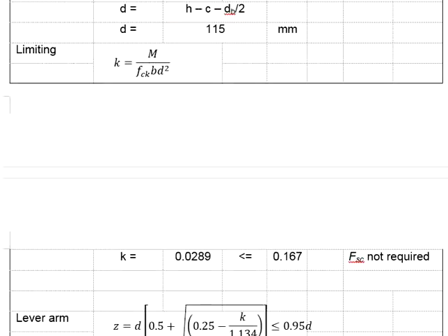Steel bar is more costly than concrete. 1 meter cube of concrete, based on the local supplier of my area, costs only a few hundreds. As a method to minimize the cost of the material, you might as well provide a thicker slab with less reinforcement, where the reinforcement is just enough to meet the minimum As. That should be the most optimum design. Therefore, by all means try to prevent the compression steel bar for a typical slab.